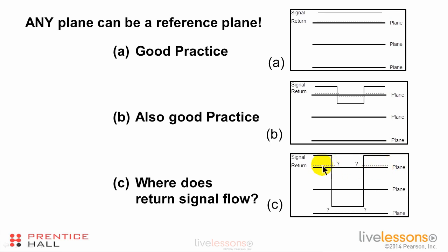The second answer is we just leave it and trust to chance that the signal is going to get there. And in our experience in the past, most of the time that's happened and we've gotten away with it. There are some system engineers and some circuit design engineers who will say you can't do this. They will set a design guideline for the board design that says you can't transition from one layer to a completely different layer, referencing a completely different plane. And if they are setting that design guideline, this is one of the reasons why. They're worried about where the return current and the return path is going to be.